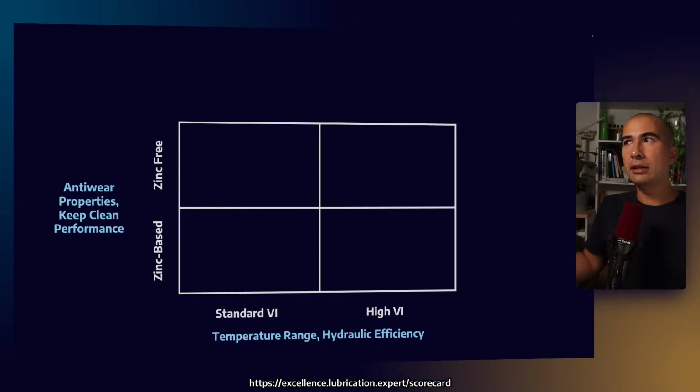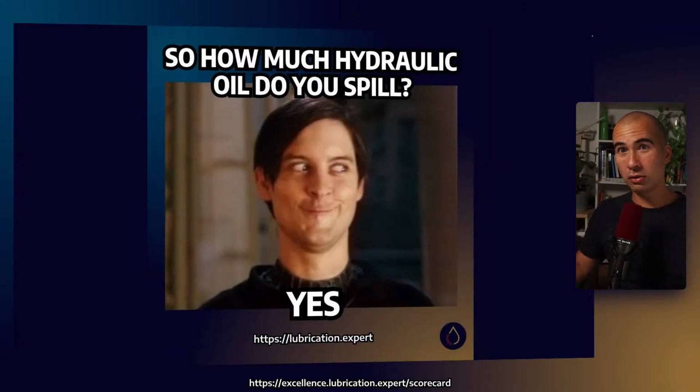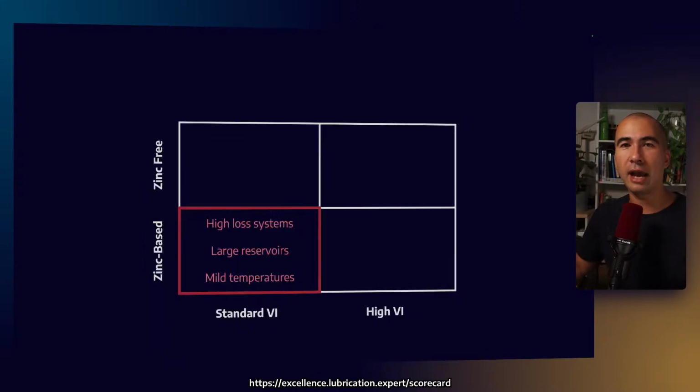Now, this is one of those cases where more expensive is not always the correct answer, because I go into a lot of sites, and if you were to ask how much hydraulic oil do you spill? They tend to spill a lot. There are a lot of blown hoses, and a lot of hydraulic oil that ends up on the ground. So before moving to any kind of premium hydraulic oil, the key thing is to fix up those leaks first, partially because it's a waste of money, partially because it's an environmental disaster waiting to happen, right?